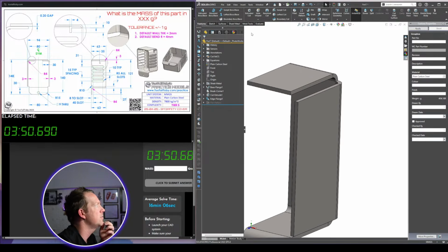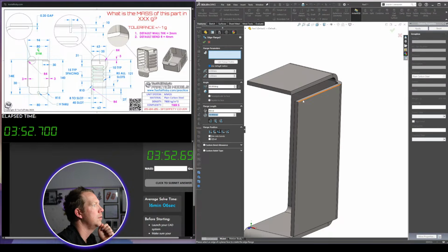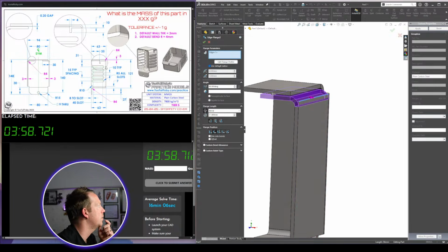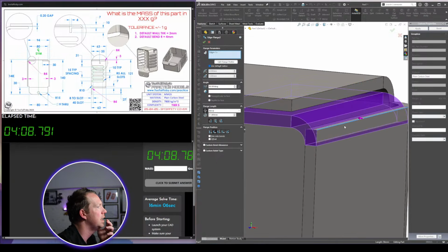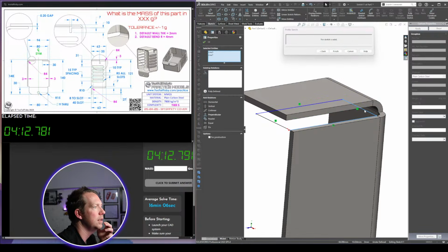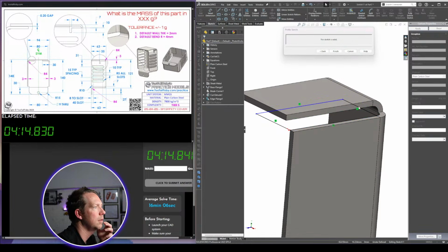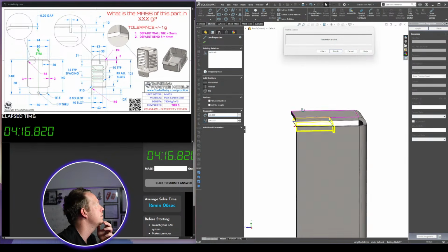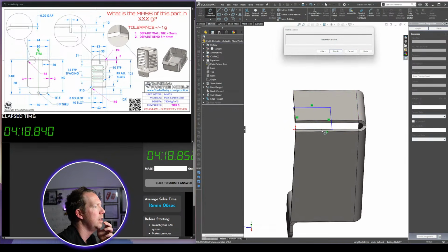Then we've got another edge flange, which is coming in the top here. But this one is going to be inside. But we actually want to get it right up on that edge. You can see it's coincident. This will actually give you an error in SolidWorks, I think. I want to offset it up. I also want to edit the profile, bring this edge in, because that is going to be 35.